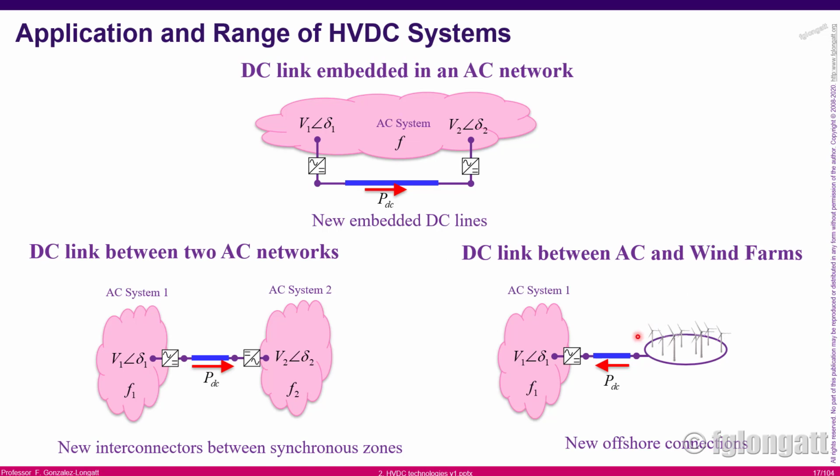In recent times, the technology related to undersea cables, and also the improvement of the power converters and the commutating devices, has made the use of DC links for transmitting power from offshore wind farms quite attractive, okay? I believe you must remember my talk about the wind farm in Germany, the Wind 1, and they are using a HVDC system. There are many reasons for that. One of them is that you have more controllability regarding the load flow. And you can also control the voltage a lot on both sides, okay?